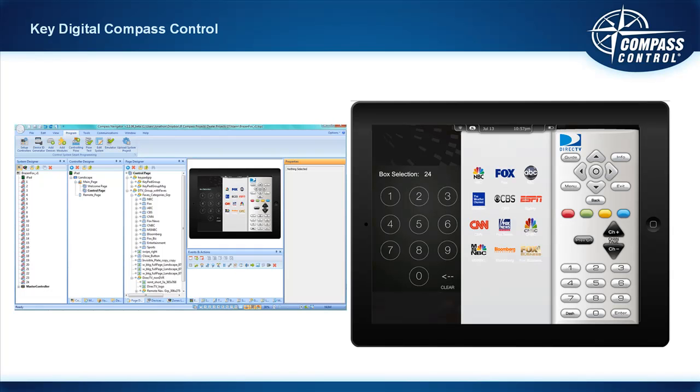When you're controlling that device from the iPad, then I taught you that the Zigbee remote actually does go through the master controller, then to the IP device. But when you're dealing with the iPad, you don't utilize any port on the master controller in order to control IP controllable devices. Now, that being said, you do 100% always need at least one master controller in the system. We see that at the bottom left corner. However, I'll have you know, nothing's even connected to that master controller.